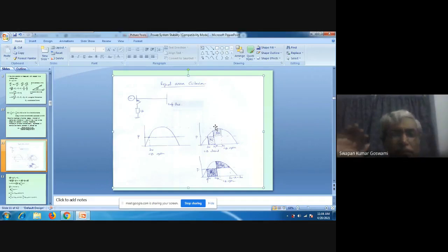We cannot express it in megawatt second because we are not plotting against time. We are plotting against delta, purposefully. So since we are plotting against delta, it is in some way representing the energy associated. But here the unit should be written in megawatt, because power is in megawatt, or the difference is also in megawatt, multiplied by angle difference in radian. So megawatt radian. This may not be actual energy we are talking about, but it is a representation of energy. It will be proportional. Simply convert that into time, and it will be the energy.